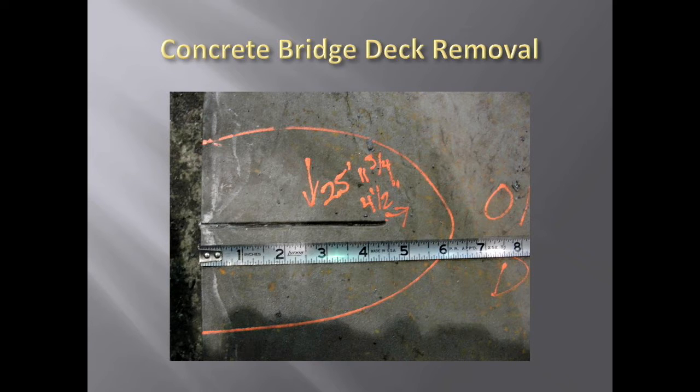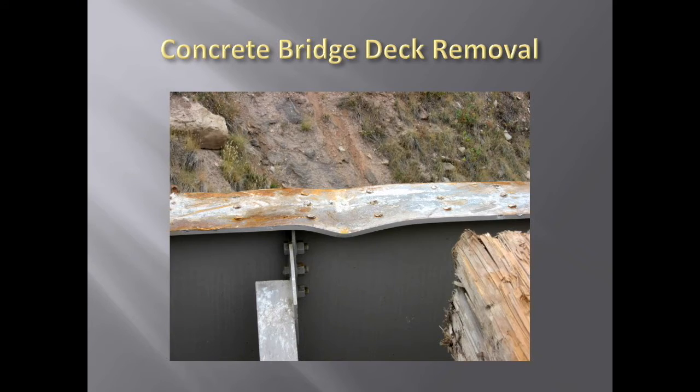This is an incident where we had them cutting the deck basically into panels, and they got into the top flange of the girder. We had to come in and have that gouged out and full pen welded, and we had to do the ultrasonic testing on it and everything else we would typically do before they could get moving. This probably holds them up 3 or 4 days at least. So on a time-sensitive schedule, that can really put a crank into things.